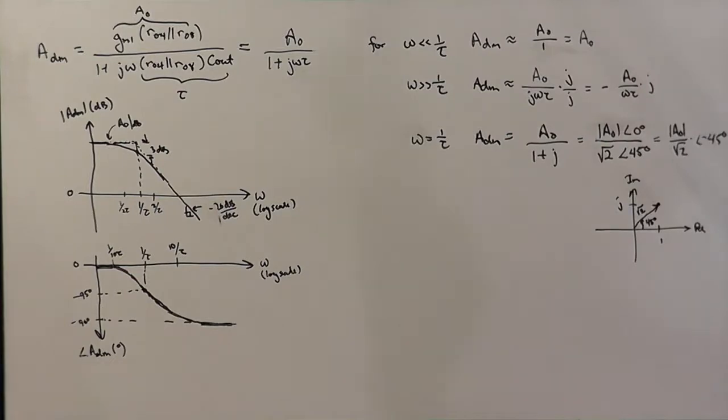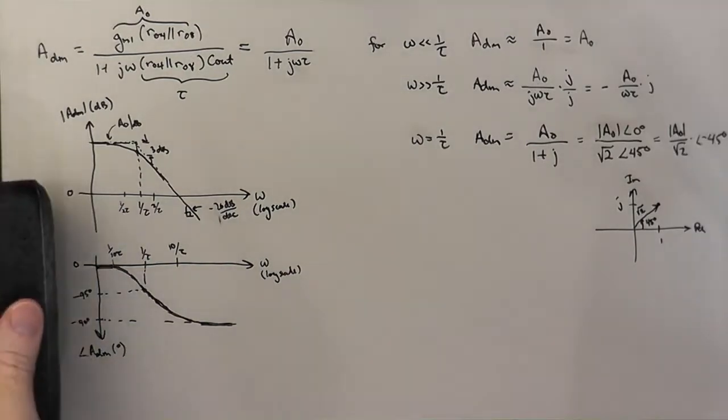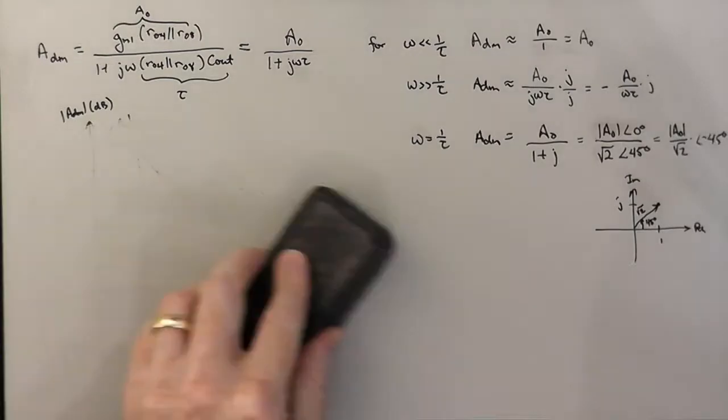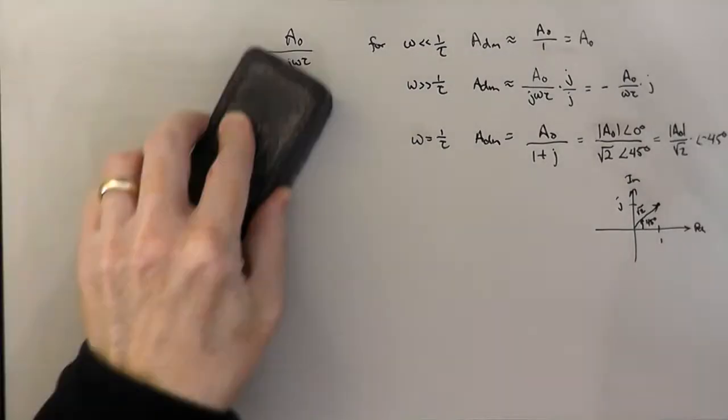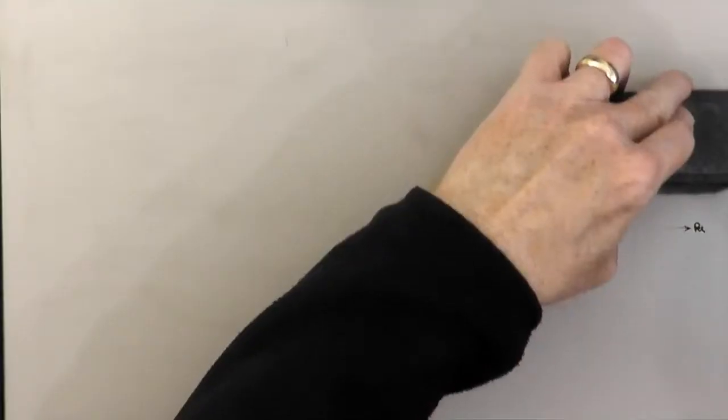Okay, so that was kind of the Bode plot representation of the gain that we found for the differential mode operation of our 9-transistor diff amp. And what I wanted to do next, with a capacitor on the output, is to consider a similar calculation, only with unity gain feedback around our amplifier.